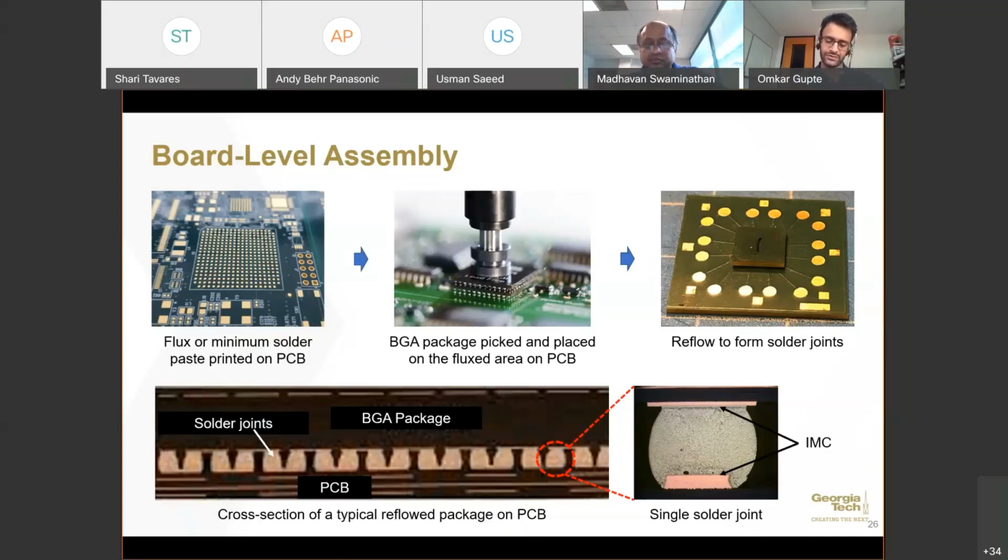Oh, so that's a good question, and it is a problem. With the NSMD, that's a challenge that comes. But on the PCB side, when you do the reflow and the processing, it's processed once, whereas on the package side we prefer having SMD because it is processed initially during the package processing, and then it is passed through the reflow during the board level assembly as well. So it goes through more process steps, which is why we would want that to be locked in.